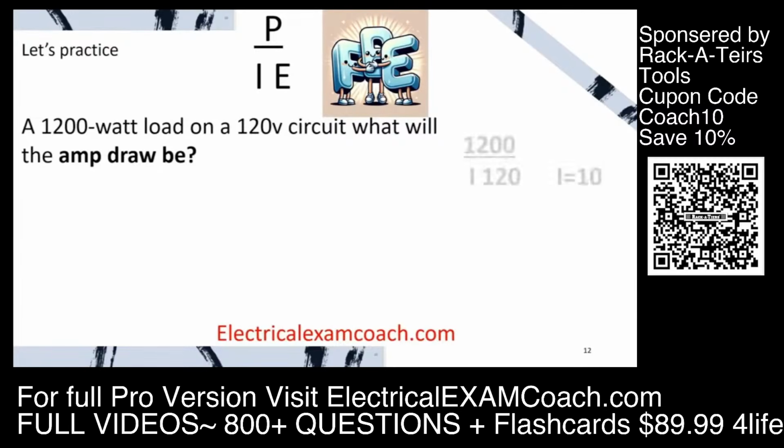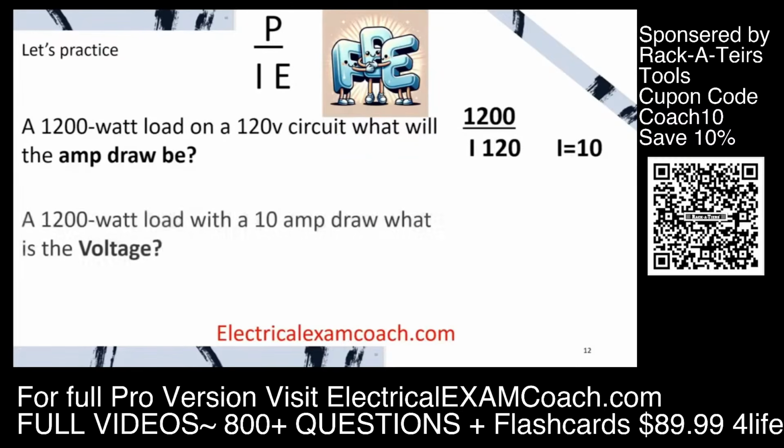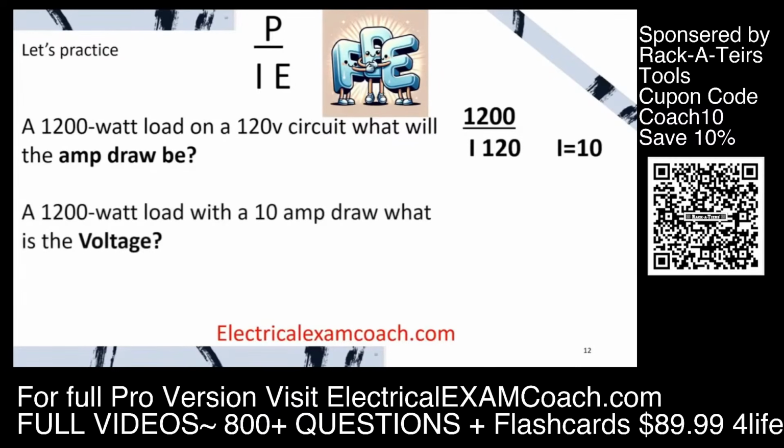Well, we just plug in what we know. We know the wattage, and we also know the voltage, and we're trying to solve for the current. And just like in the previous formula, all we have to do is divide. So we divide it out, and we end up with 10 amps. We have a 1200 watt load with a 10 amp draw. What is the voltage? Well, let's plug in what we know.